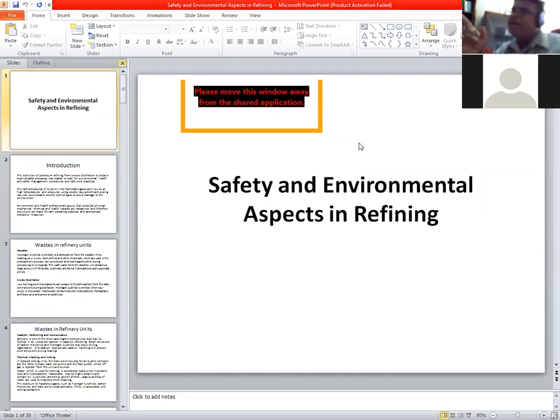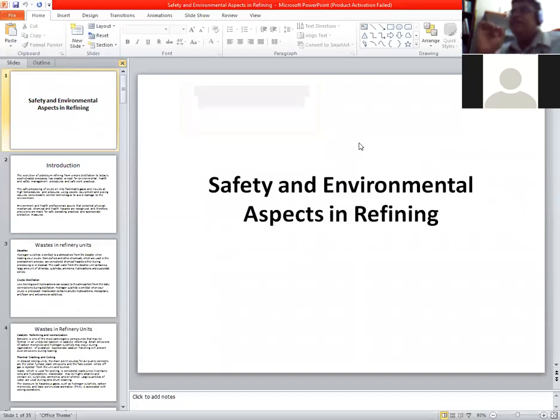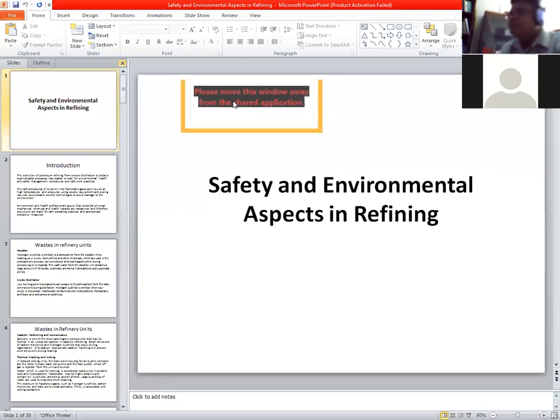That is actually called vapor cloud explosion, VCE. It is very common near any petroleum refinery if there is some leakage. So if leakage is there, it has to be immediately rectified. Otherwise, this hydrocarbon leakage, whenever it leaks to the air, can accumulate and it can explode. That is called vapor cloud explosion.